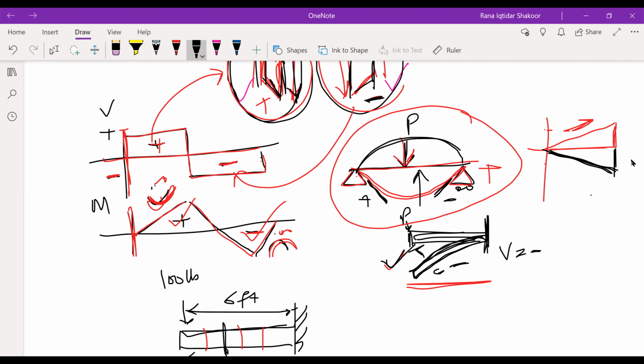And what about the shear? You see that everything in this section will be like this, because it is continuously coming downward, right. So this is up, this is down. Net is basically like this one, counterclockwise, and we know that counterclockwise is always a negative shear force, right.